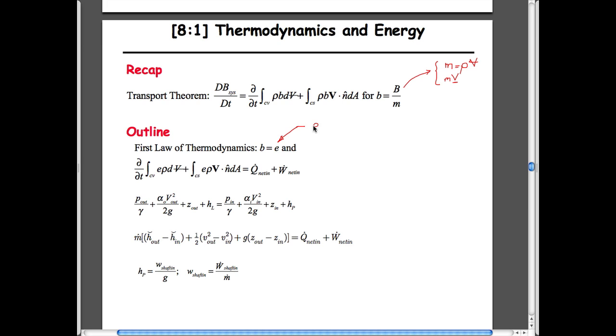And so energy, as we define in lowercase b, is energy per unit mass. And so energy per unit mass we can define as due to the components of internal energy plus the kinetic term, v squared over 2, plus potential energy, which is just elevation times gravity. And that's what goes into this. This is energy per unit mass that we'll attempt to conserve anyway.